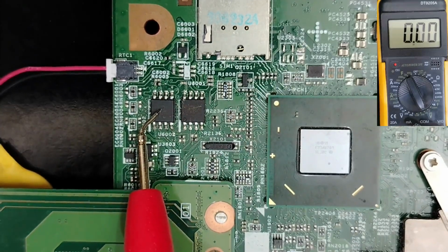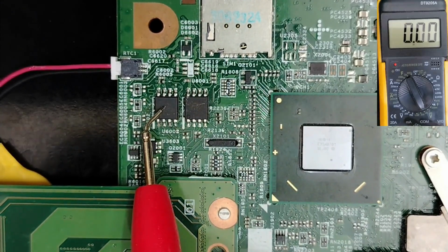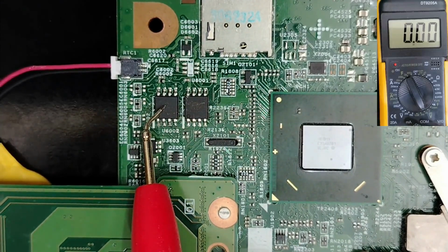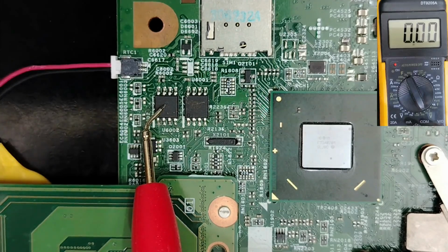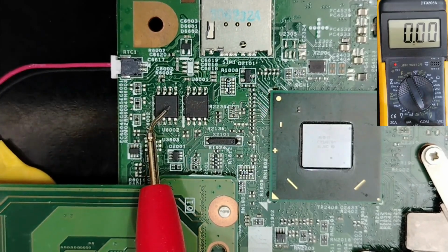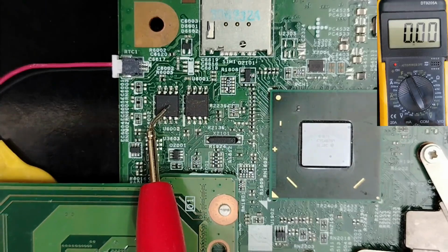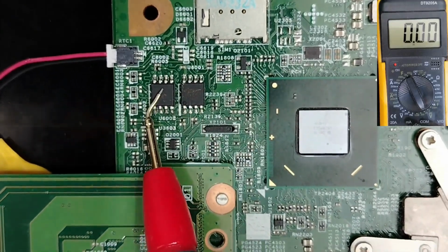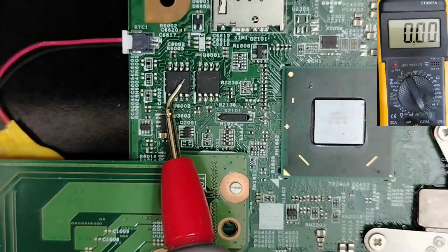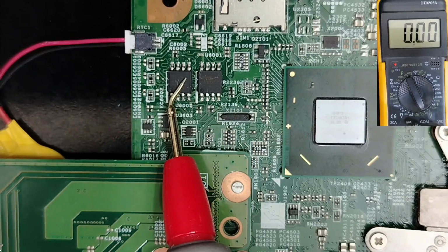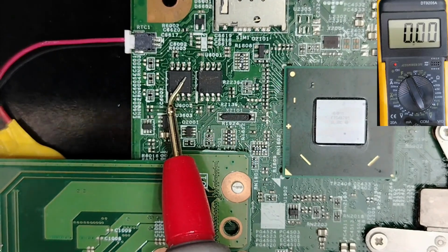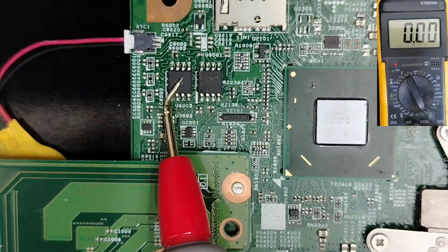BIOS receives its working voltage 100% successfully. Okay, so the BIOS should work 100%. If it doesn't work, it means the firmware inside it is the bad one. And how can we know if the firmware is good or not? When you get a new boot laptop or you get a black screen, you have LEDs on, but you have a black screen. All these signs mean you have a problem with the firmware.